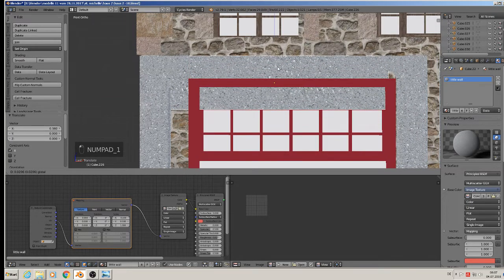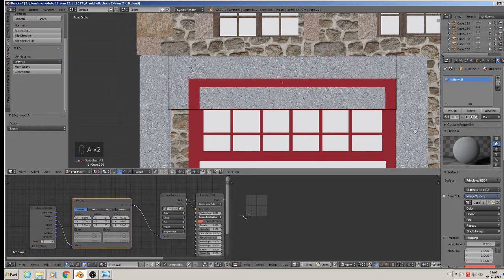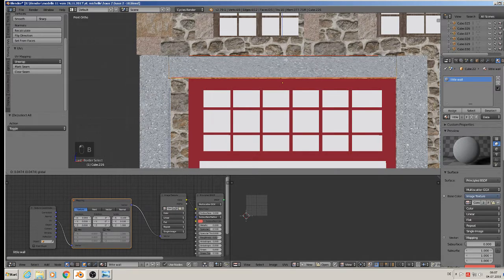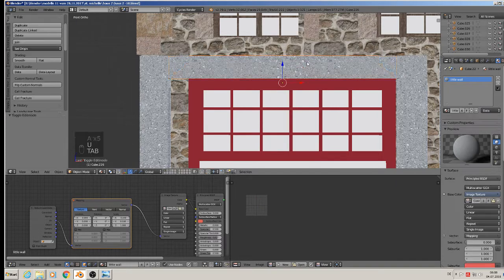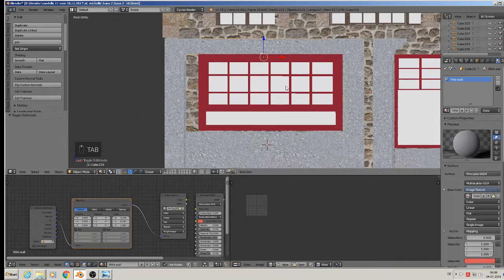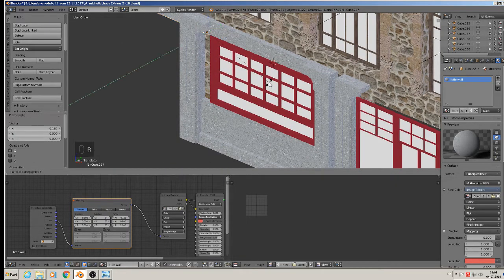where texture should be. So that here, we only need to bring them up. So we close here. Then we need to unwrap that new. So U cube projection, take that, Shift D, bring it here, rotate Y 90.